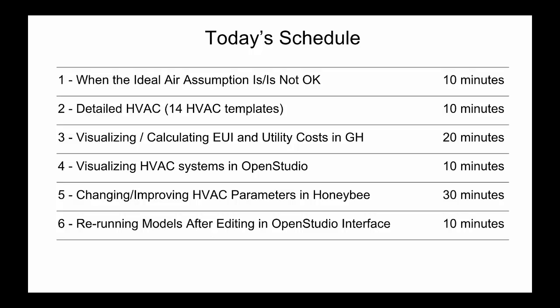It's an office in a cold climate. But really, a lot of this is going to be geared towards showing you exactly how to use these things and pointing the way, especially for advanced users, so that you're able to run simulations of pretty detailed HVAC. First, because everything we worked with last time had to do with an ideal air system, I'm going to talk about when that assumption is and is not okay, and when you have to switch over to a detailed HVAC energy model.